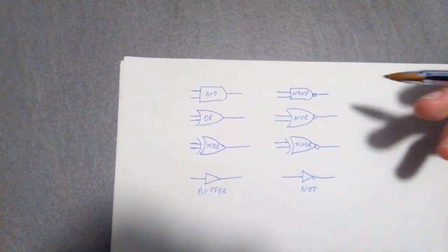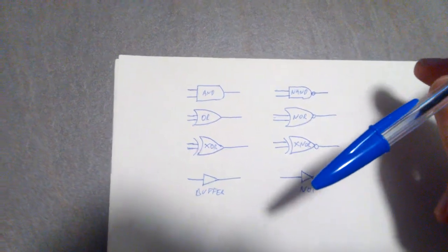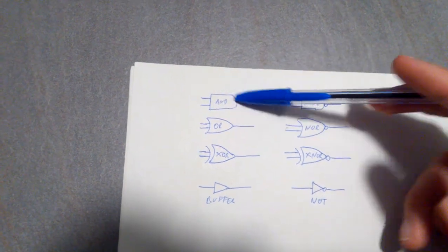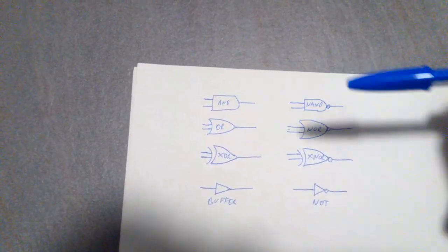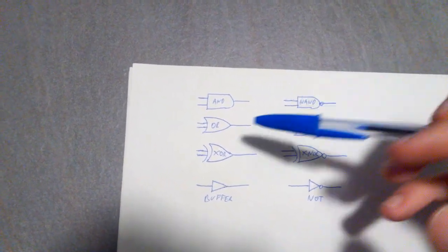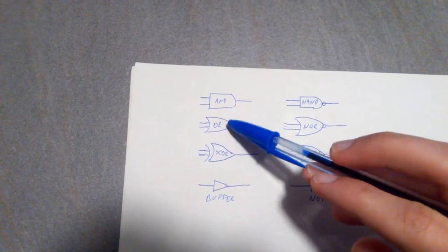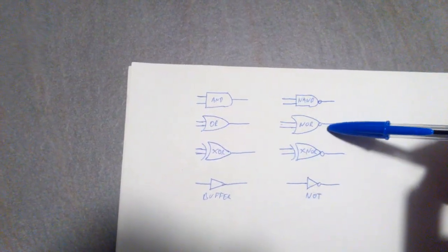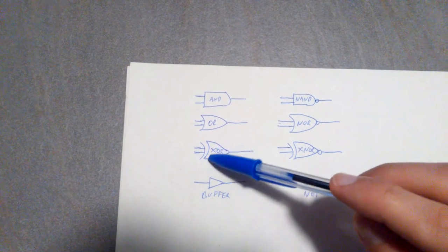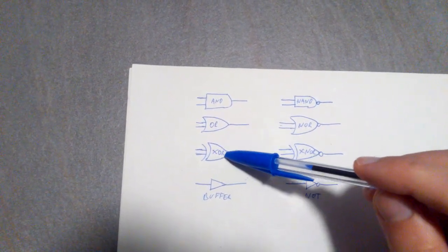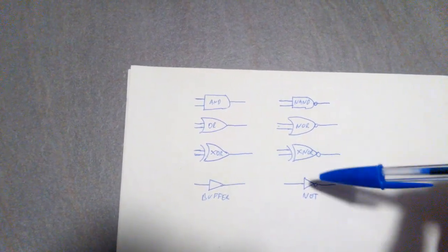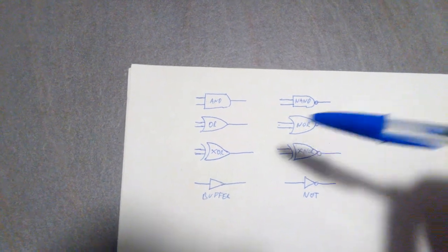We have been using all those gates pretty extensively within these lectures. For the AND gate, both inputs have to be 1. The NAND gate is the same but with a NOT, so everything is inverted. For the OR gate, at least one of them has to be 1. If they're both 1, then it's fine. NOR is the same but inverted. XOR, exclusive OR, means at least one of them has to be 1, but if both of them are 1, then it's not going to be valid. Exclusive NOR is the same but with a NOT.